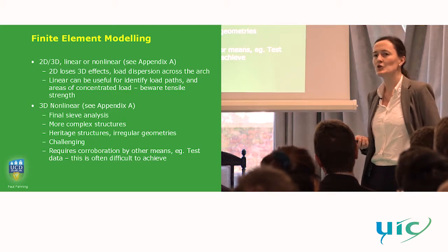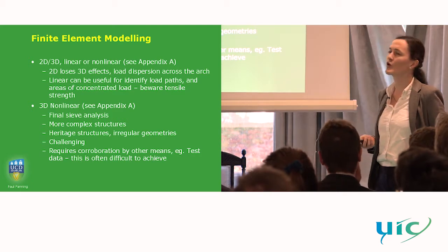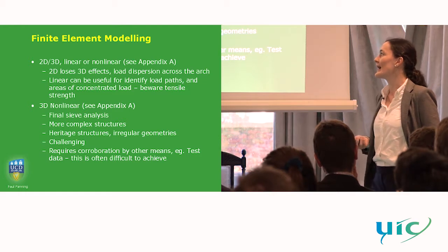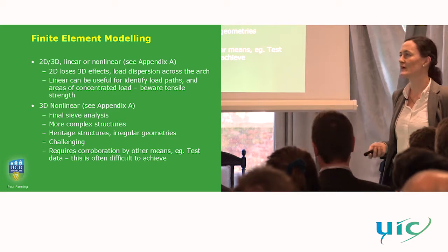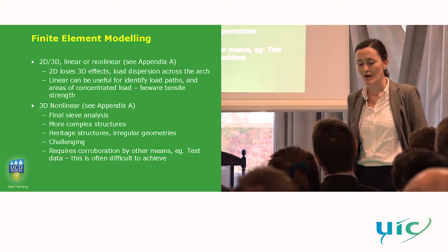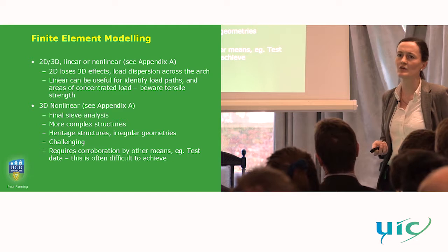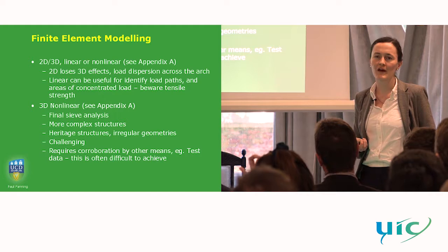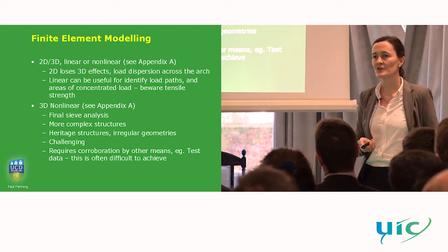So they're not for routine assessment. You couldn't apply them across your bridge stock. It tends to only really be justified for more complex structures or more complex problems. Generally, it's where you have a very challenging problem, and therefore you're taking a more time-consuming and challenging approach. From our own experiences in UCD, this does require a certain amount of model validation, and therefore test data to go along with it.